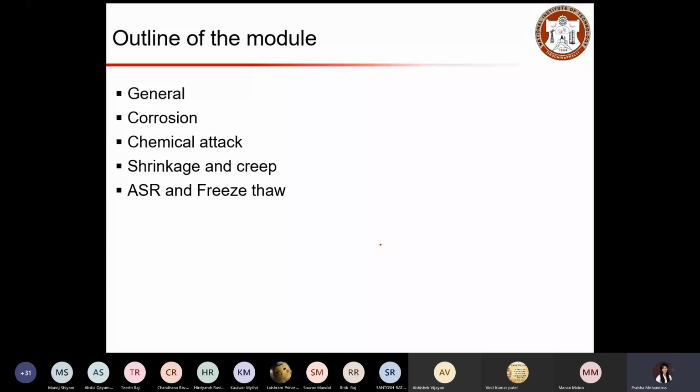It could be corrosion, which would first deteriorate the concrete and then affect the steel reinforcement that is there. So corrosion is mostly associated with steel behavior. If your concrete is not good, that will allow other elements like water or oxygen and chlorides and some carbon dioxide to enter into concrete.